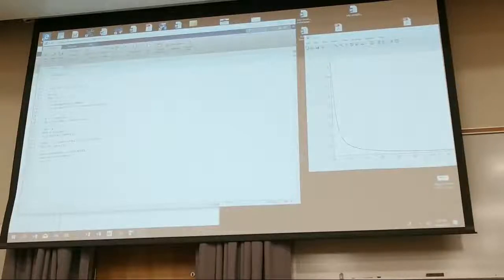The real thing I'm trying to tell you here is this will allow you to look directly at frequency domain information as if it was a Fourier transform, even though it's a finite signal with a lot of other crap in it usually, and you'll get noise and stuff like this. But this is pretty clear that it shows how amazingly similar these two are when the frequency of sampling is high enough. You follow me?